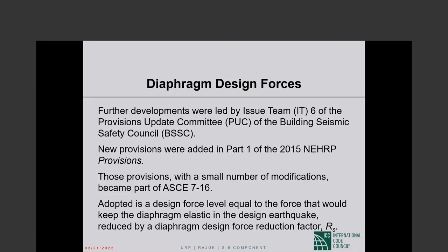So, there is one question referring to a previous lecture. You have calculated the live load reduction factor based on IBC 2009. R is equal to 0.08 times some area, where area is in square foot. The alternative approach for the live load reduction factor is not available in BNBC 2020. Can we still use that IBC 2009 equation for reduction of live load?